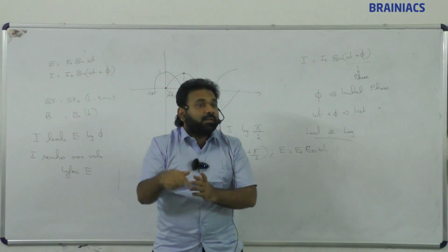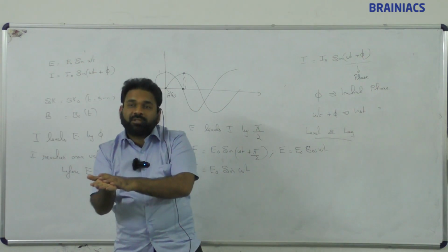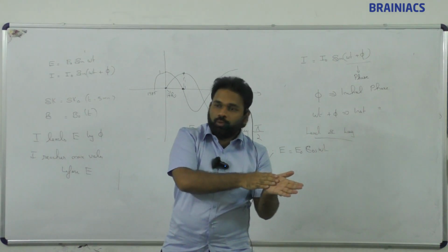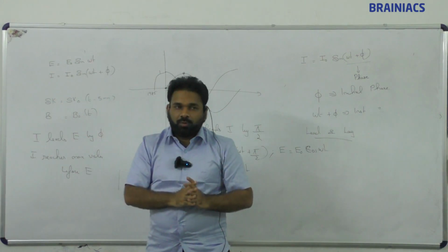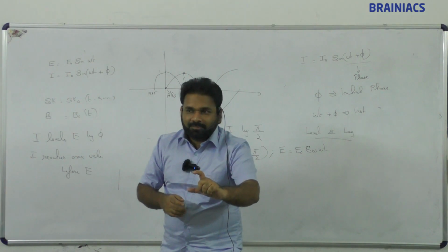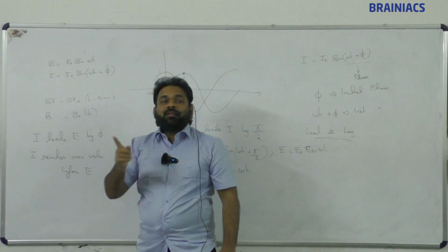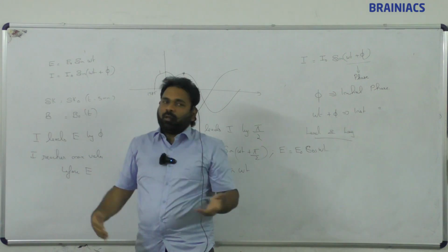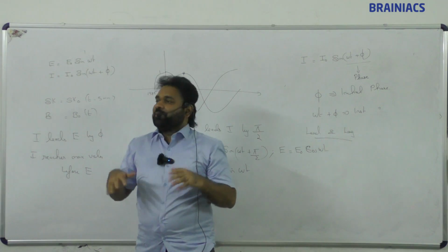Seeing that, then what we will do, accordingly how much current is possible if it is DC. Is it clear? Once again I will repeat, how much heat is delivered, say for example 5 joule. So I square RT if we do, how much is that current? If we see that, we will be able to show some measurement. That is what is RMS value. So I square RT in DC is I square RT. I square RT in AC is I RMS square RT.